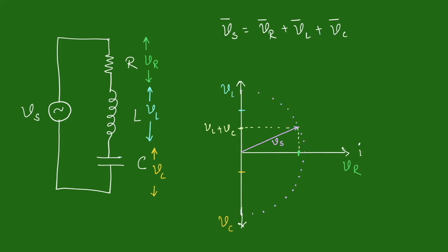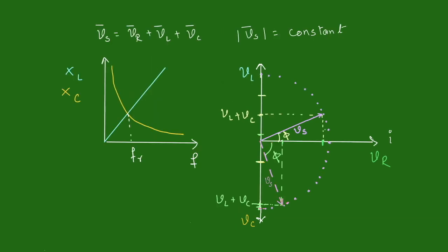That shows that as we go on increasing the frequency beyond FR, the phase difference between the applied voltage and current in the circuit will go on increasing, and it will take the maximum value of 90 degrees when the frequency becomes much greater than FR, where Vc becomes negligibly smaller than VL. When Vc becomes negligibly smaller than VL, we can say that the circuit is going to be an inductive circuit.